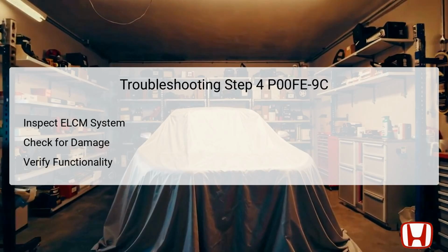If a blockage or damage is found, repairs or replacements may be required. If no issues surface, it's a good indication that the ELCM is functioning as designed. However, further testing may still be warranted to confirm its efficacy in relation to the overall EVAP system performance.